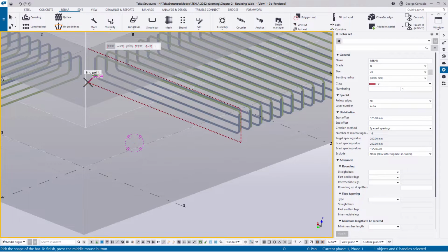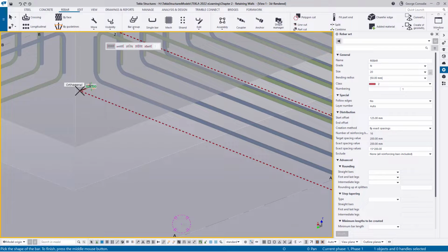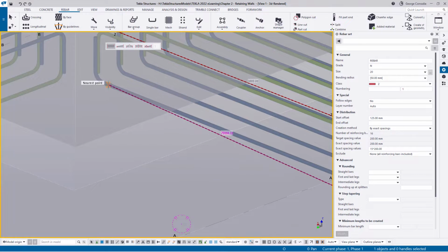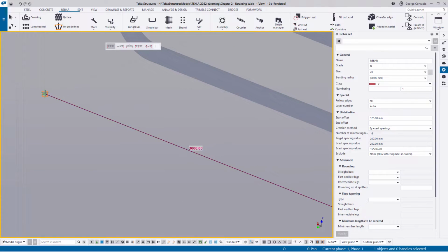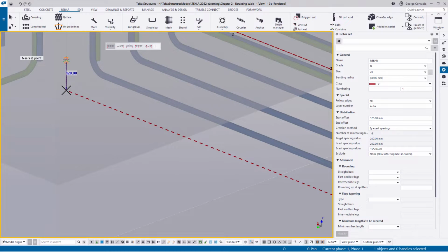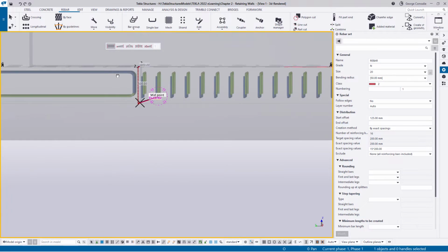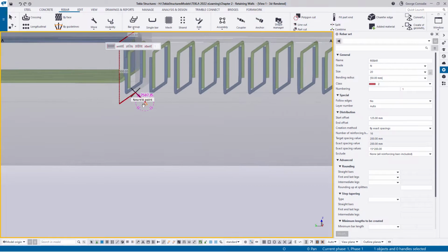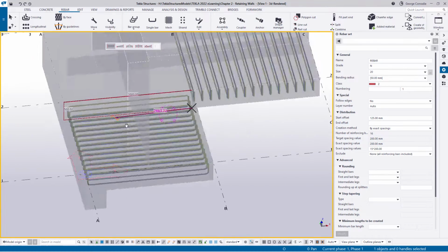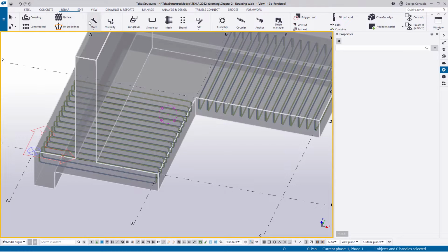Didn't accept that. Back corner. I think we just undo that. Undo that again. Undo, by the way, is just the backspace. Just make sure you click the right thing. So if you get a red bar like that, it means it's an invalid input, and you can be sure that somewhere you didn't click properly. So what we'll do is we'll escape out of that and just try it again.